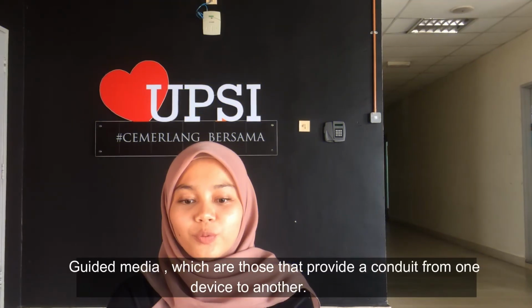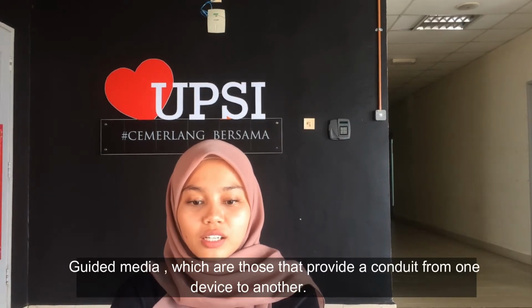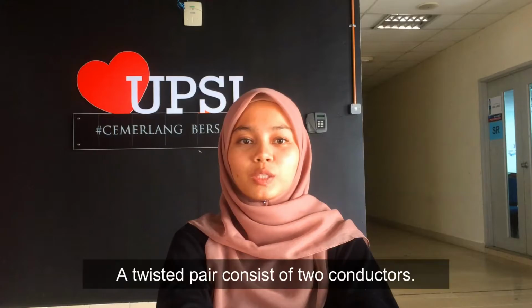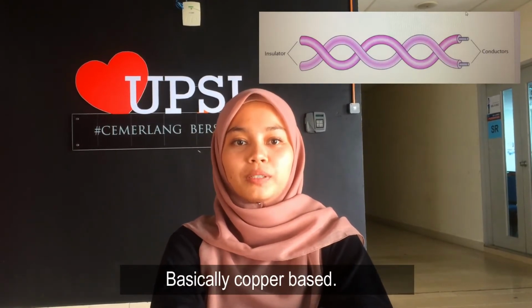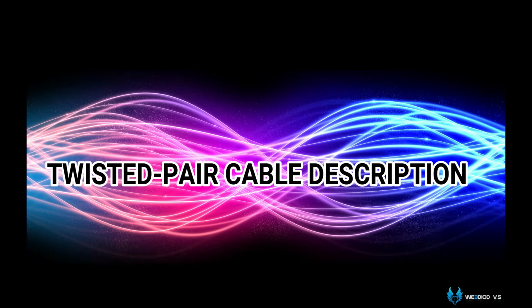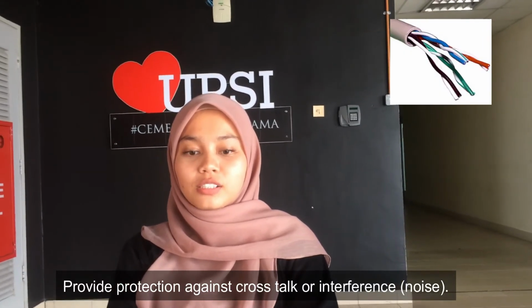Guided media, which are those that provide a conduit from one device to another, include twisted pair cable, coaxial cable, and fiber optic cable. Twisted pair consists of two conductors, basically copper wires, each with plastic insulation, twisted together. This provides protection against crosstalk or interference noise.